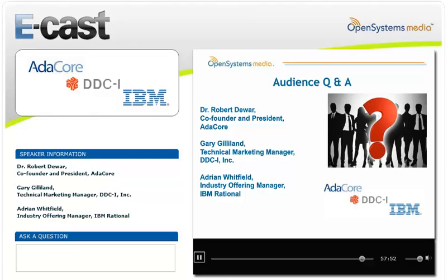Right. So currently, as I discussed in the presentation, we support the ARMs with the MMU technology, which is typically the A8, A9 technology currently. There's also the Altera hardcore IP for the Cortex A9. Since we're supporting an SoC model, there's a lot of these, such as the Xilinx and others, that we would have the core support as well. It would just need minor tweaking for device interfaces on whatever platform they would be on.